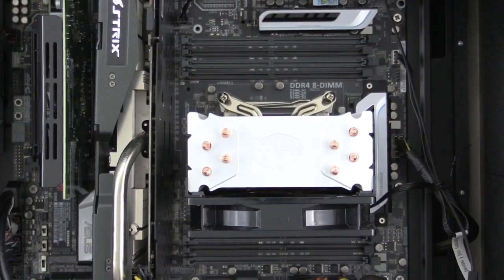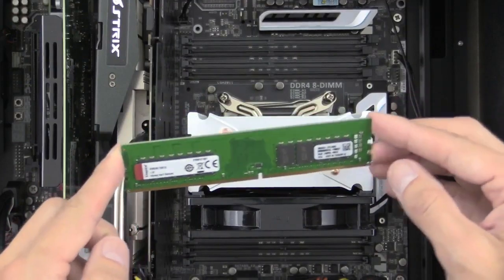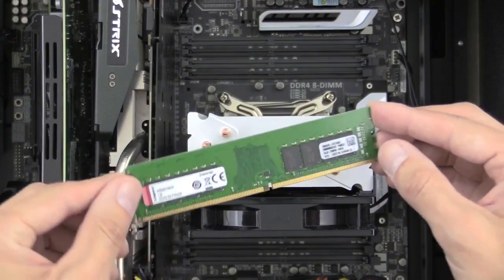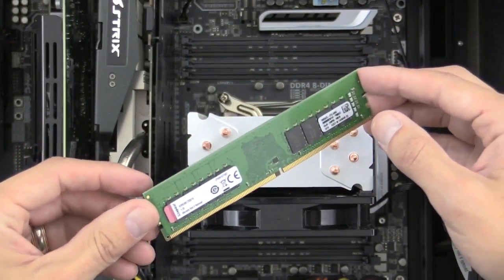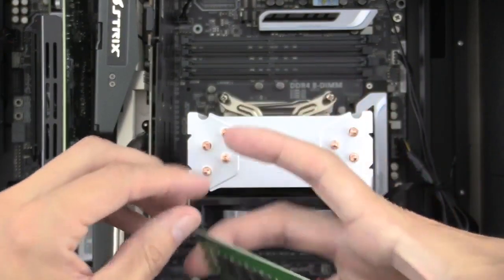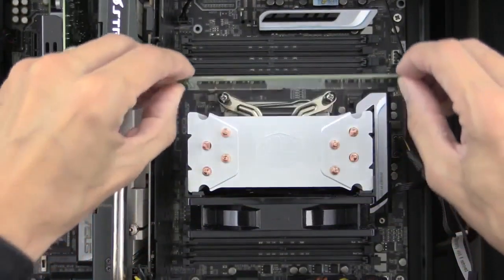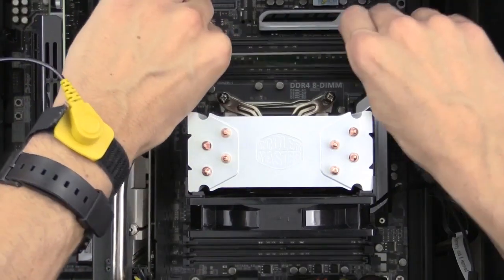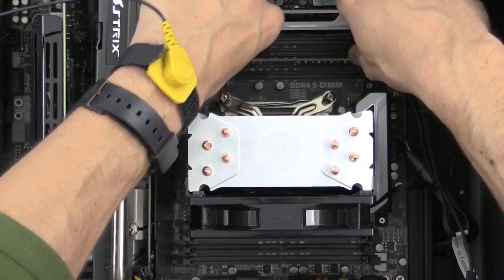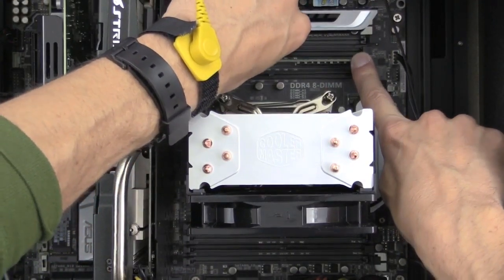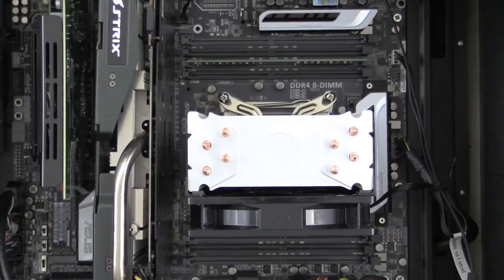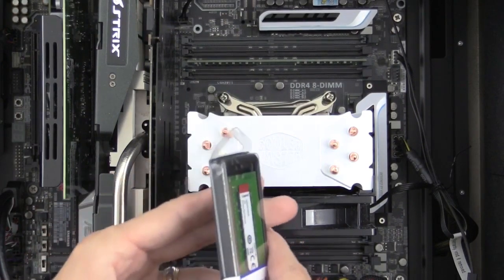To install the RAM, we can take it and make sure we're just holding it by the edges. And you want to line up the notch in the middle there into the slot properly. So for this one, we have to turn it around. And then we can place this directly into the slot. So it's got to be placed straight in. We'll press down, and when we do so, it should lock automatically. You probably heard a snap, and it locked in. That is our B1 stick.